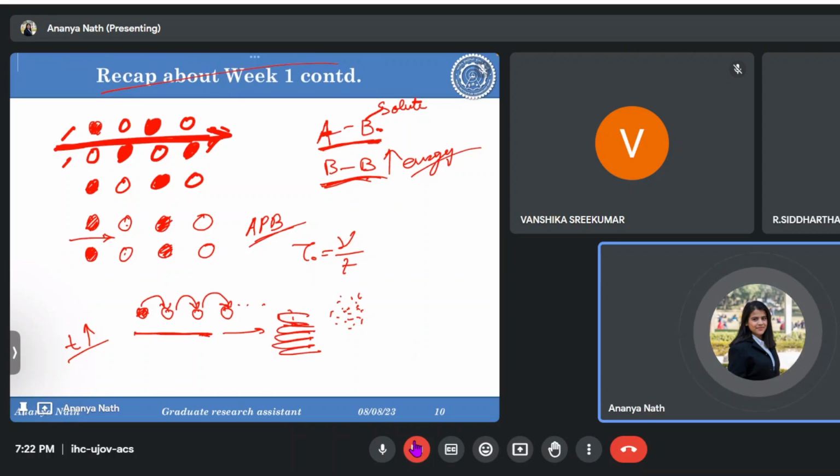At that time, solute atoms jump from one position to another for their mobility, because they will try to catch up with the dislocations, and therefore solute atoms lag behind the dislocation. As I said, the dislocations will move with a very high velocity, but the solute atoms are jumping from one place to another. First they are finding one vacant position nearby, then they are jumping, so obviously it will take more time than